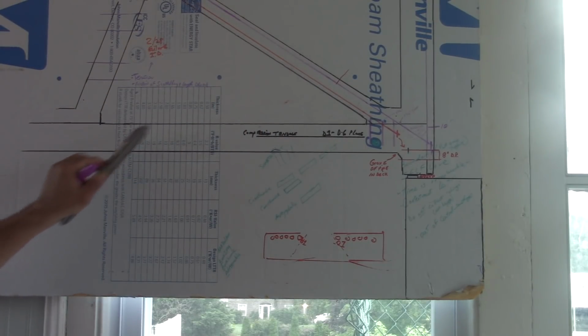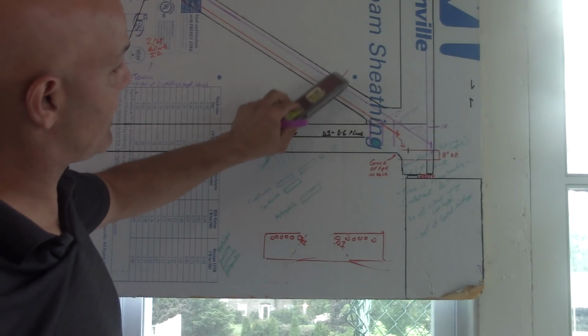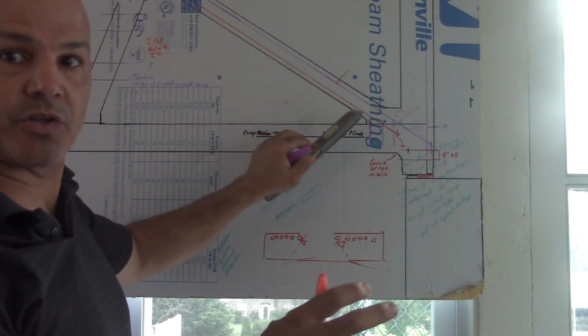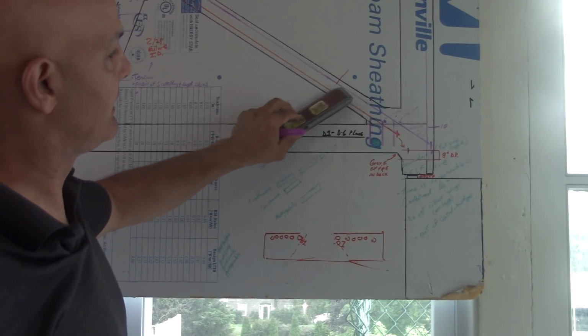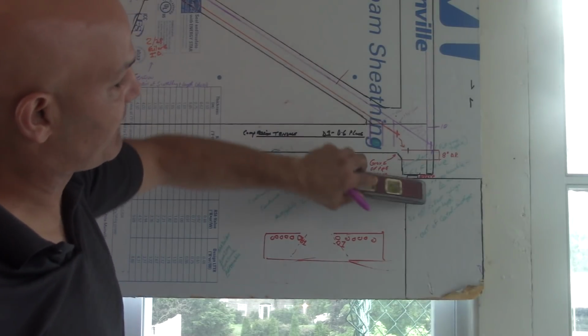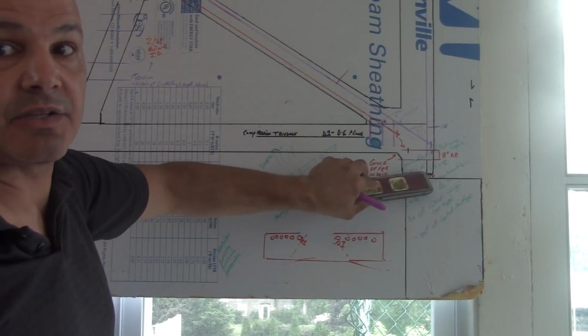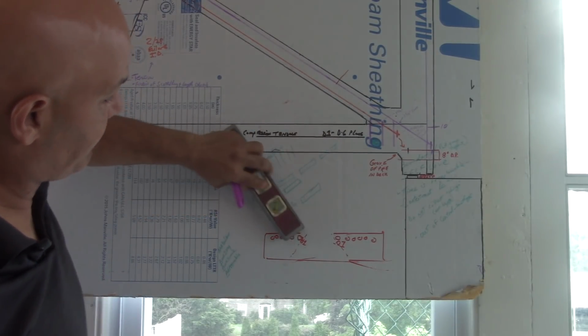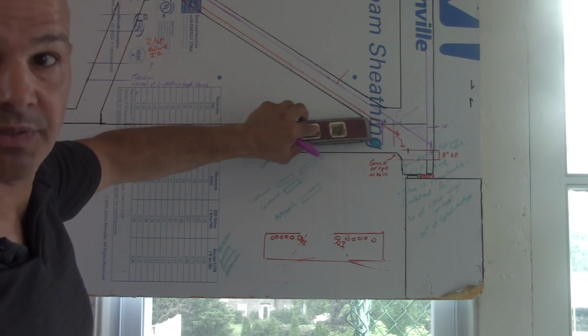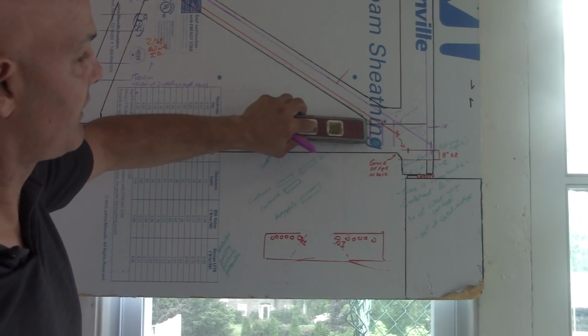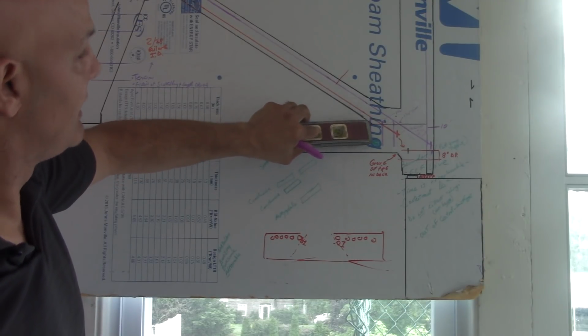But what would do it at all? Again, you release the post-tensioning rods A and B, but you leave them on taut, just with your hands. You back them out. When they did that, that dropped down into that grout area, which we know now has been measured. It presented itself the first day as very small cracks, and I'm going to show you down below on my foam board. Very small cracks right about here.